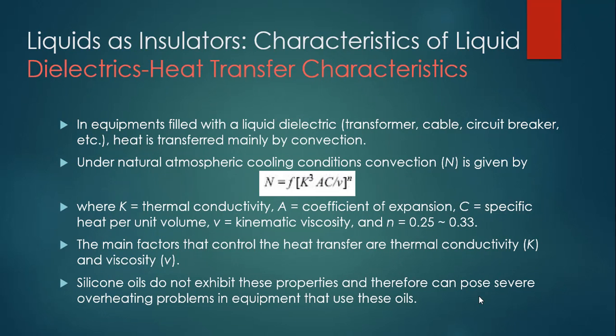Now we'll talk about the heat transfer characteristics in equipment filled with liquid dielectric, that are transformers, cables, circuit breakers, etc. The heat is transferred mainly by convection.